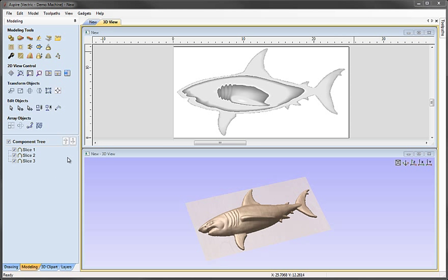Slicing the part so that our job is just slightly bigger than the component has really allowed us to maximise the potential quality for each of those slices. Now though, we need to increase our job size in order to create a part which is actually the size of the piece of material we plan to cut, and then make copies of our slices in order to get all the components we're going to need for the finished job.